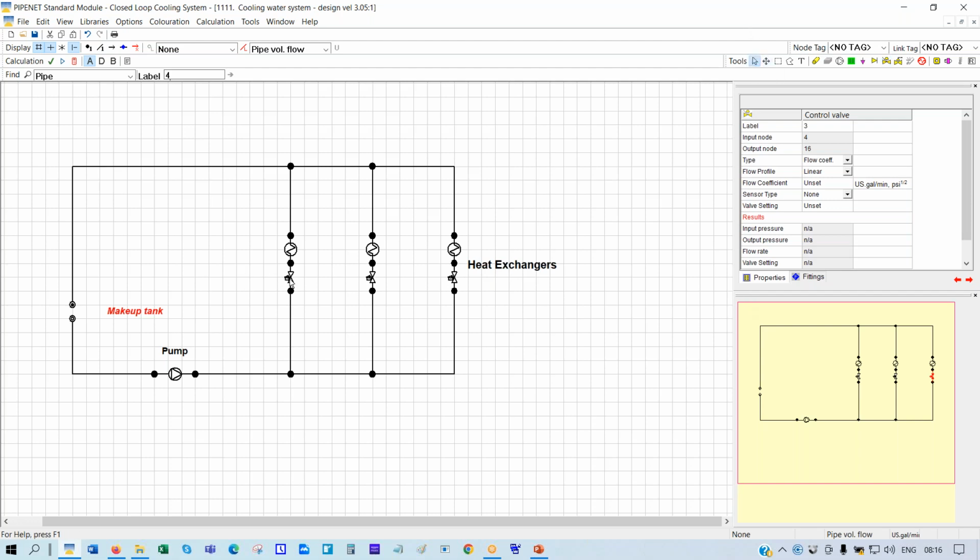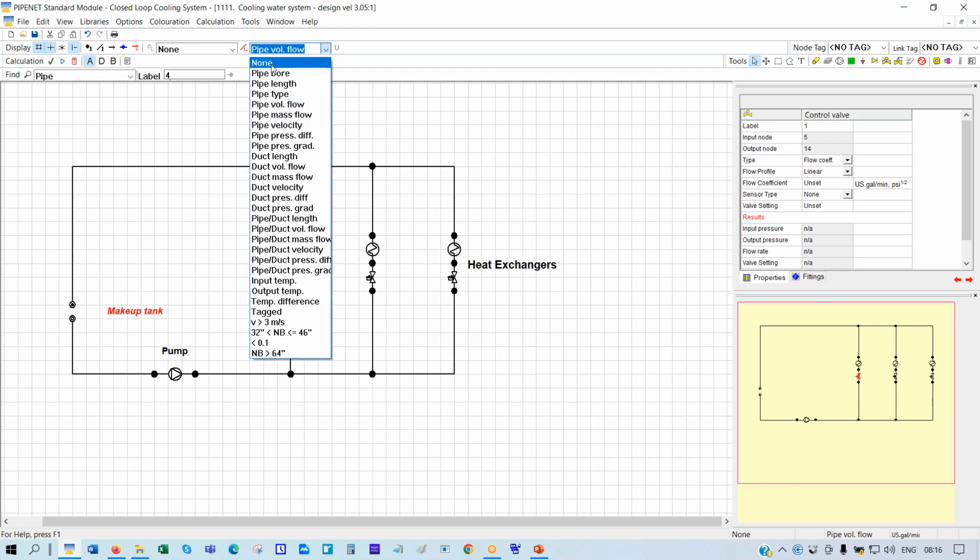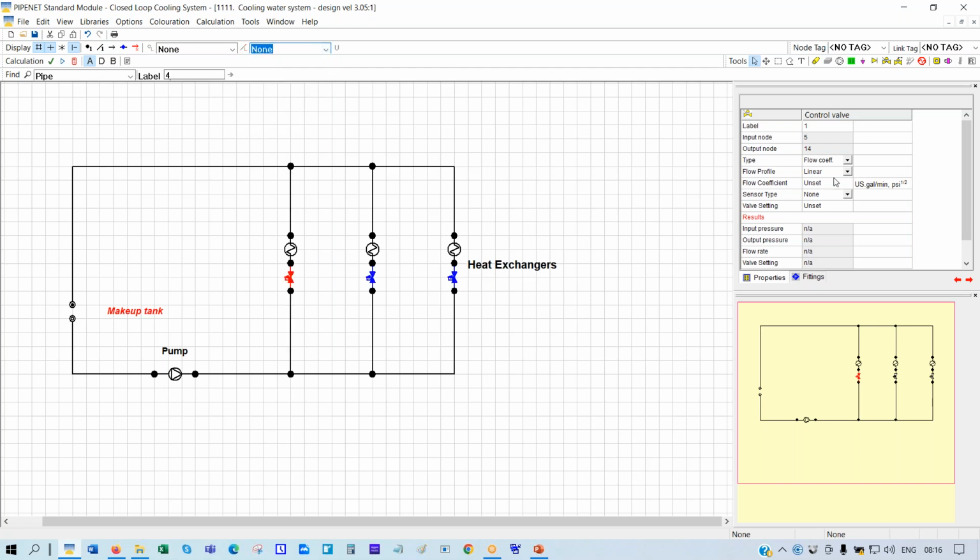So I'm going to click on that, and I'm going to specify the attributes. See, from the previous calculation, I know that the CV at the operating point of that valve is 131. And I've written all that down.